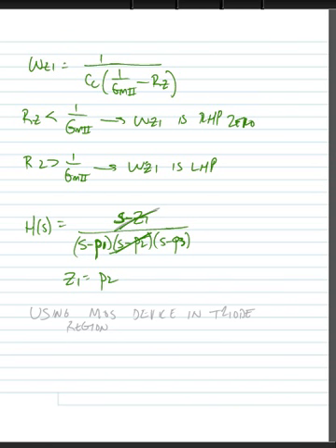And we're going to do so by using a MOS device in the triode region. So we're going to make our resistor, our nulling resistor, out of a MOS device. And the way we make resistors in MOS devices is to use them in the triode region. And we will look at sizing that MOS device in the next slide.